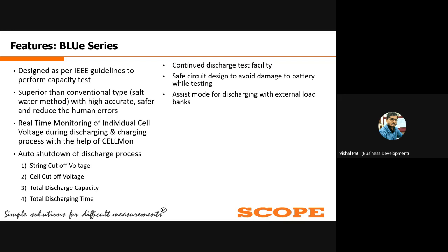Now if you have a battery loading unit of 30 ampere and a conventional resistive load bank with a capacity of 20 ampere, then our battery loading unit can monitor the 20 ampere current from the external load, and it will maintain its current so that you will get the total current of 50 ampere. That type of smart feature we have incorporated in our battery loading unit.